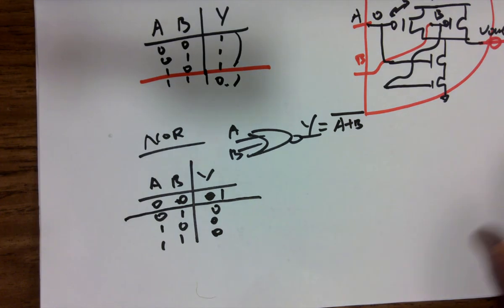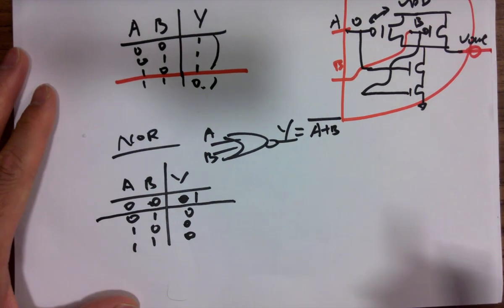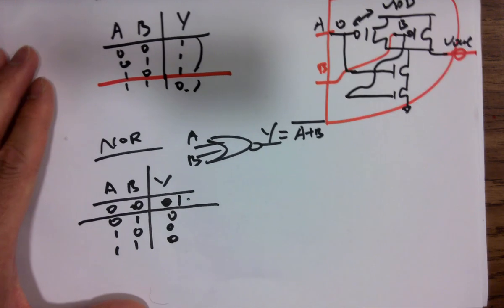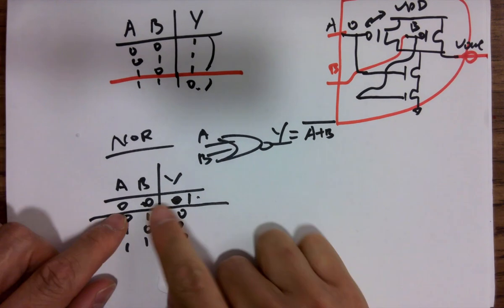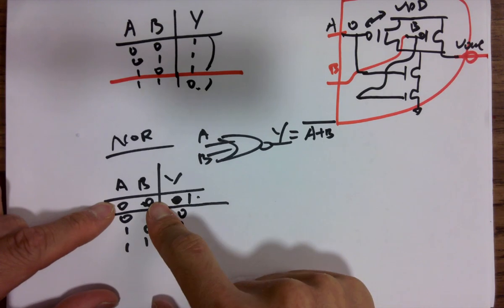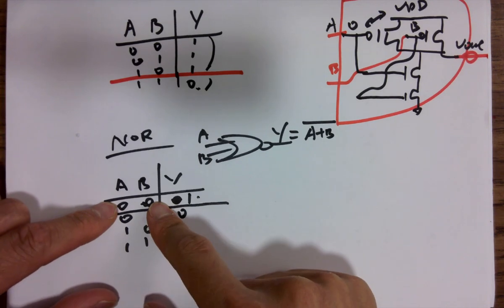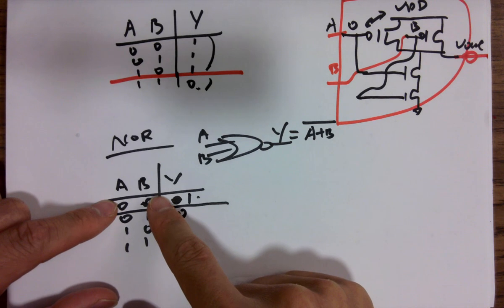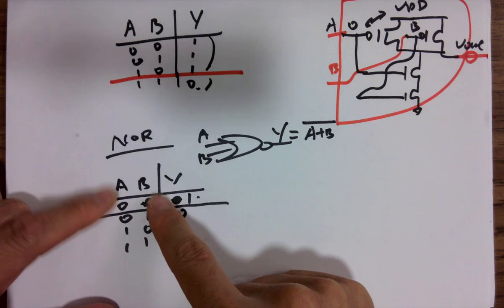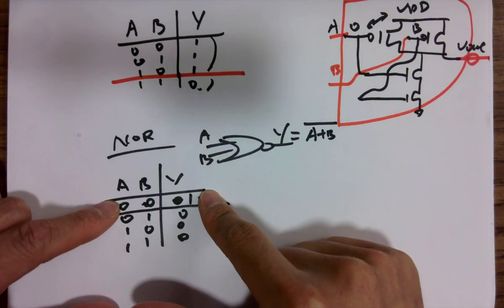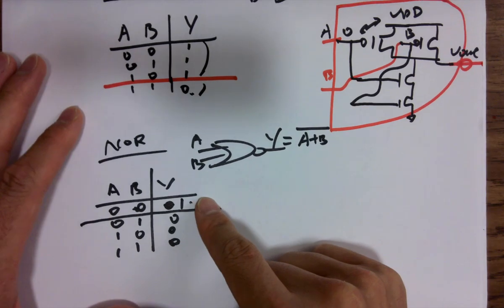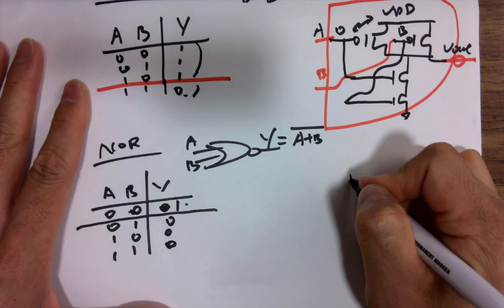So divide it into sections and let the PMOS combinations figure out the top entry. So 2 zeros means what? 2 zeros at the gates of the PMOSes means what? They have to be on at the same time. The PMOSes need a 0 to be on, right? So the two PMOSes have to be on at the same time in order to pull this up to VDD, to 1. So how do you want to connect the PMOSes? In series? Two PMOSes in series.